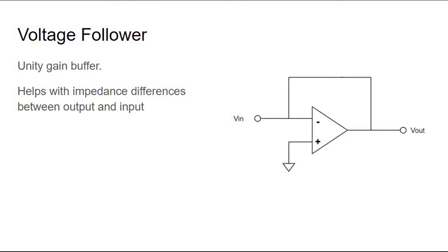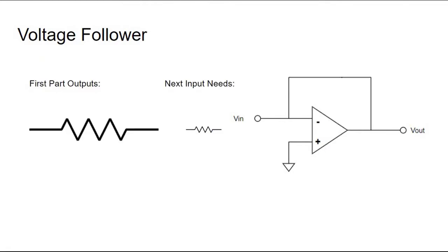Let's start with a very easy setup, a voltage follower. The feedback loop stabilizes the open loop gain so that the output voltage follows the input voltage. A voltage follower, just as the name implies, will have the output mimic the input, so your Vout equals Vin. Yep, it sounds very useful, behaving just like a wire. Well, actually, there is some merit in doing this.